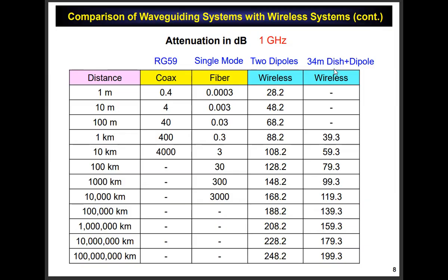Now if you scan down here, of course, you've got that 1 over r squared. So you're going to get more and more attenuation as you go further away, right? But the attenuation in dB is not proportional to distance anymore. Instead, you have a fixed increment of dB every time you increase distance by 10. So going from here to here, 20 dB. Here to here, 20 dB. And here to here, 20 dB. That's different than saying the dB is proportional to distance, right?